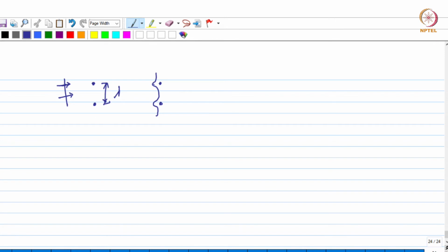And then for them to actually totally bend and bypass the particles, this curvature has to increase, right? So as it progresses more, this curvature will increase so that the dislocation can bow around the particles and bypass them. And ultimately, as it bends around, it is going to bypass.